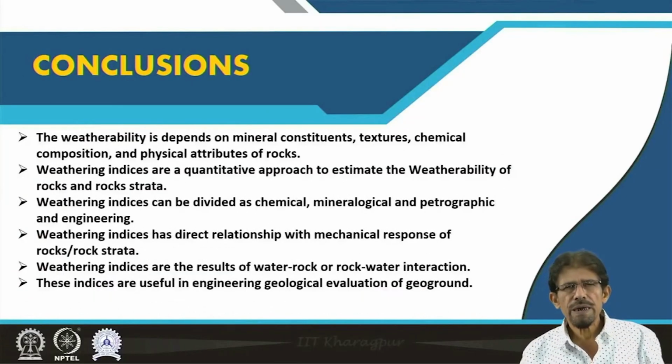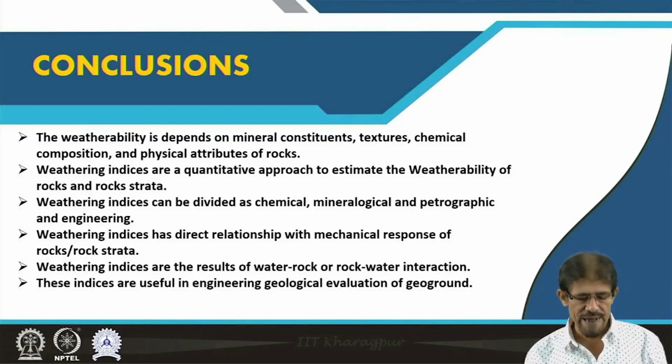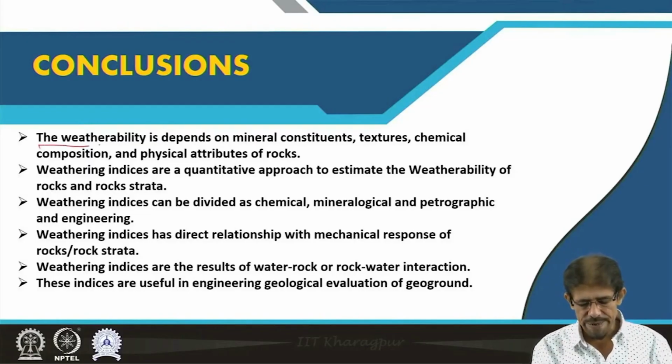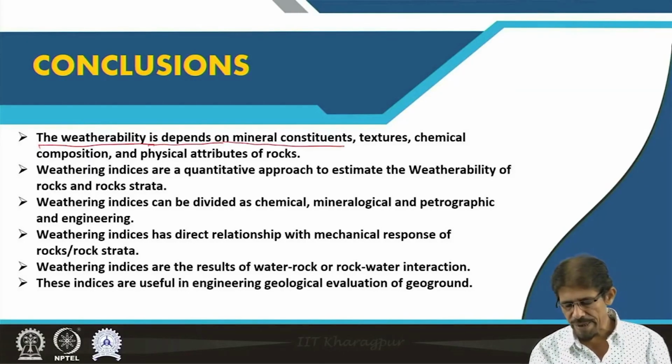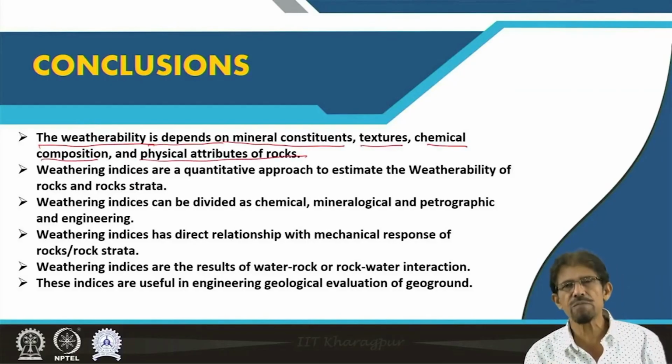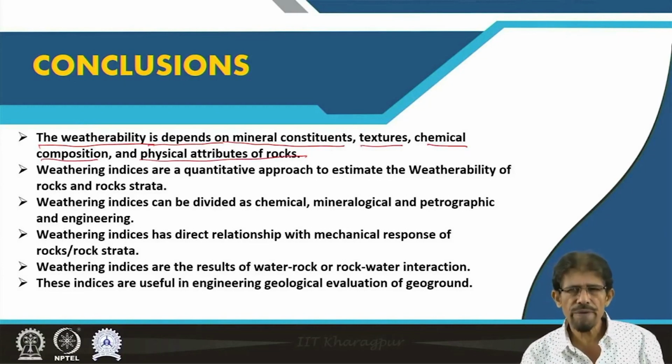If we conclude, we can say that weatherability is dependent on the mineral constituents, texture, chemical composition and physical attributes of rock. Therefore, we utilize three types of indices: chemical weathering indices, mineralogical and petrographical indices, and engineering indices.